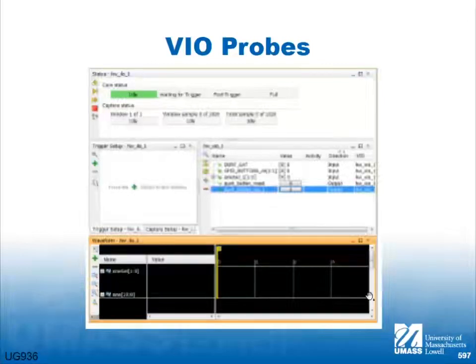There's a lot of other stuff you could do with this, but I'm limiting the discussion to what adds value to verification, and that is how you would set up simulation in hardware. Now, if you're building a giant ASIC, the whole ASIC is not going to go in the FPGA. But if it has one computational element in it that you're trying to simulate, then you put that one computational element into the FPGA, and now you can talk about exhaustive simulation.